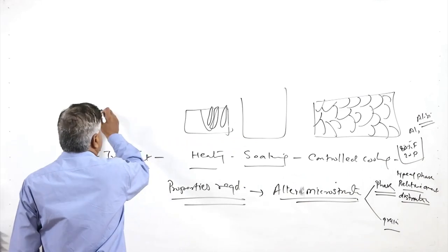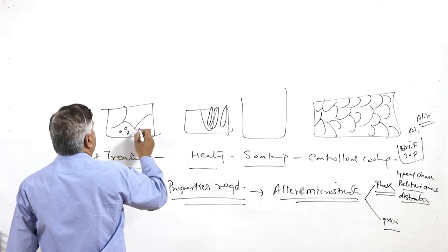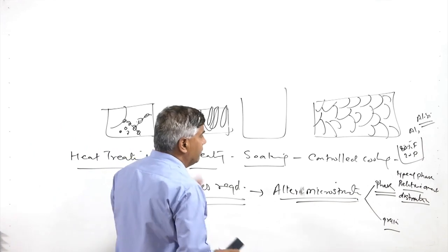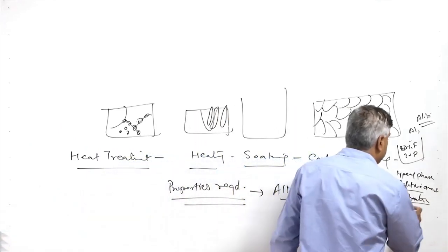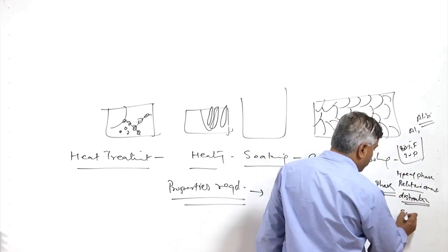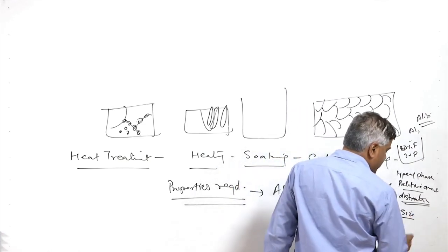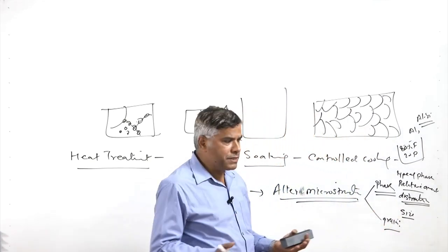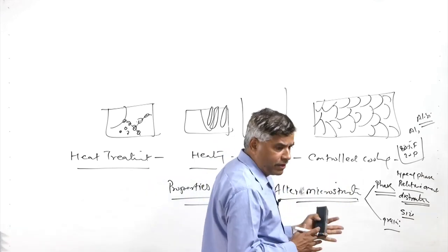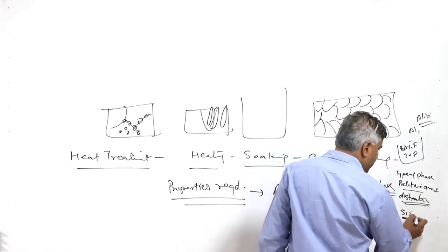And even if we consider the given metal, some of the things may be present within the grain, or some of the things may be present at the grain boundary. So, where what is present among the phases is identified through the distribution of the phases. For the grain structure, there are different ways to measure the grain size, like the average diameter of the grain, or the interdendritic spacing, or intercellular spacing, depending upon the kind of structure which we have. The grain size is measured in different ways.